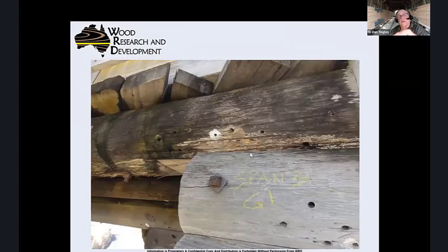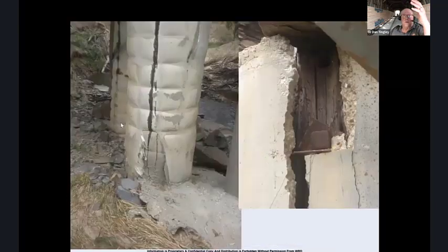He does bore sounding. You know what bore sounding does? You just drill a bunch more holes and let more termites in, when you can use non-destructive testing using drilling holes. So he says, okay, well, these piles must be settling. They're almost 100 years old, and they must be settling all of a sudden. So I guess I'll wrap them with a concrete wrap. I'll put in a steel cage. I'll use a polyester zipper wrap, put in dry mixed concrete.